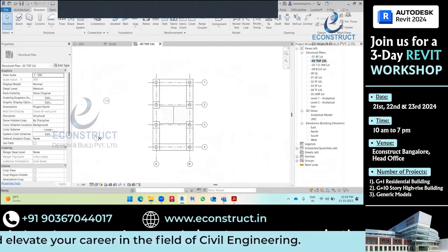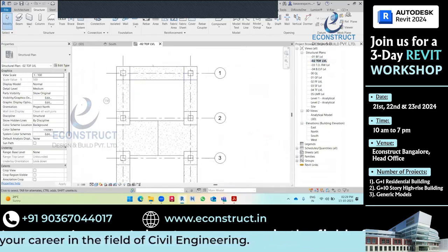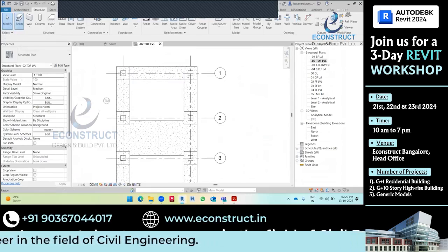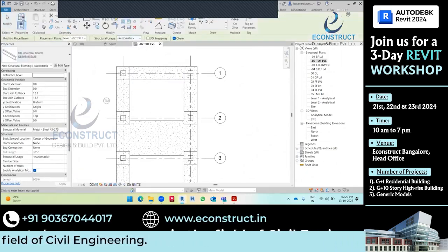So go to the top of the footing level. Select beam. Same procedure. Placement plane is top of the footing level, and you can check this chain option if you want, or else no need to check. Now it is checked, it is enabled. Chain command is enabled.